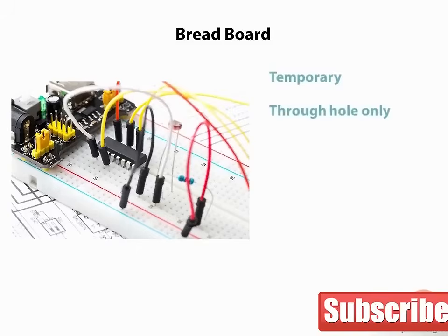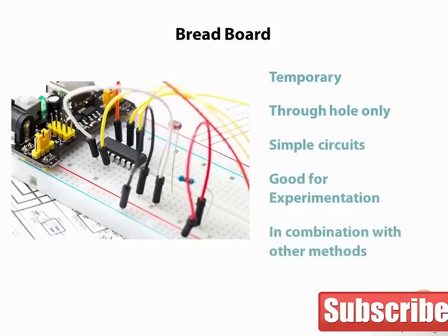They are generally only suitable for through-hole components. Surface mount components are nearly impossible to implement into a breadboard without special fixtures. Complicated circuits are more difficult with breadboards. Breadboards excel for simple and quick experimentation. Complexity can be increased using a combination of methods such as circuit board shields and header strips.